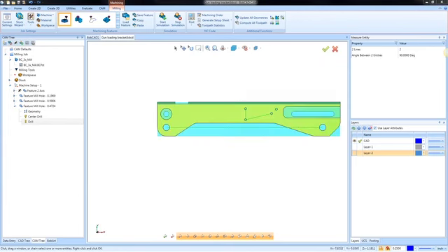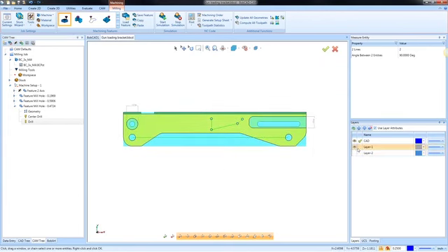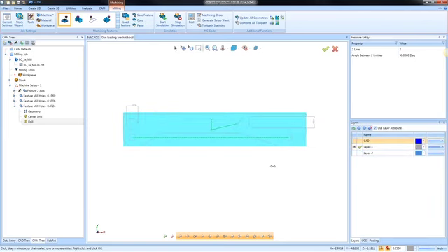One of the things that I love about the BobCAD system is you can work with wireframe or you can work with surfaces and solids. If I go to my wireframe layer here, maybe you got a DXF file from a customer, you can go through and just select the wireframe geometry. The only difference with that, Paul, is that the wireframe geometry doesn't read the depth in Z, so you just have to enter the depth in Z. It will default to 0.5, so it'll default to a 1/2 inch depth, I believe, and then you can override that and tell it how deep you want to go.